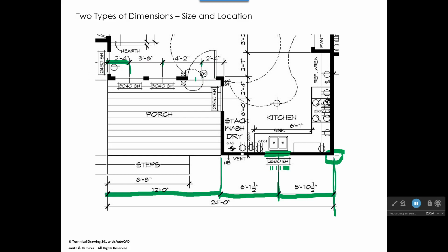And so if you look at this door, you can see where the hinge would be right here. That's the hinge jamb. Where the door closes right here, where your lock would be, that's called the strike jamb. Okay. So we've got the hinge jamb and the strike jamb, and then it says 3.0. That means it's a 3 foot 0 inch door. And right here, you can see there's two S's with a line through it like that. That is a switch that's on that wall.